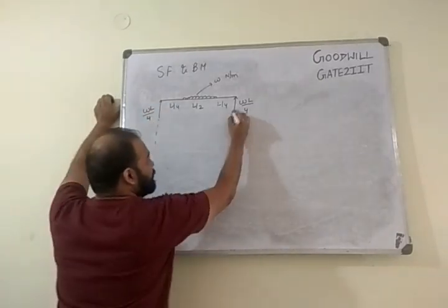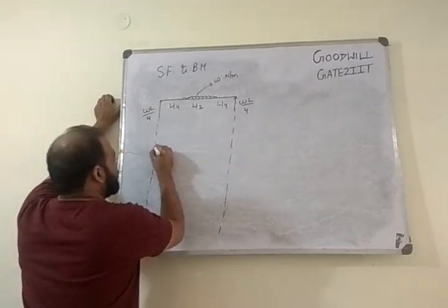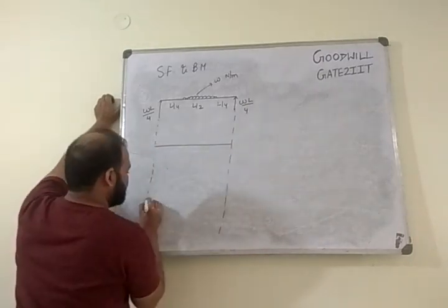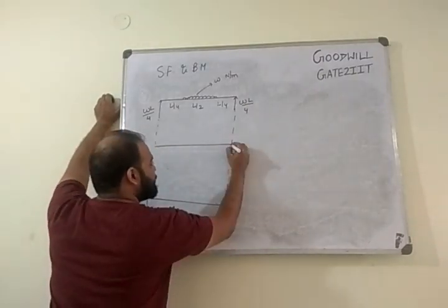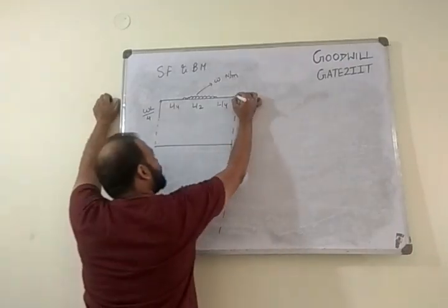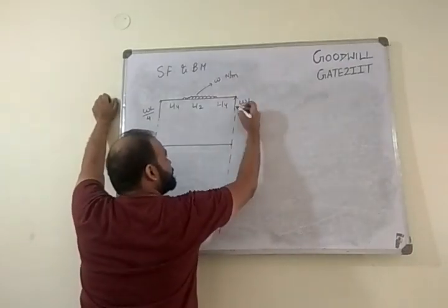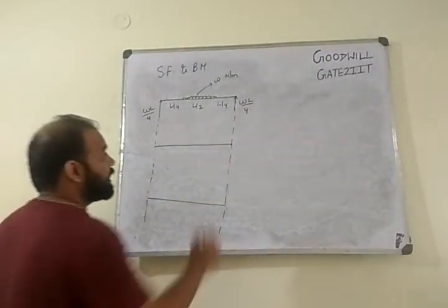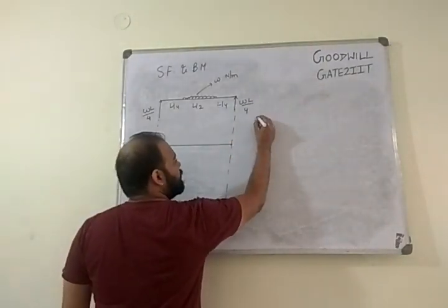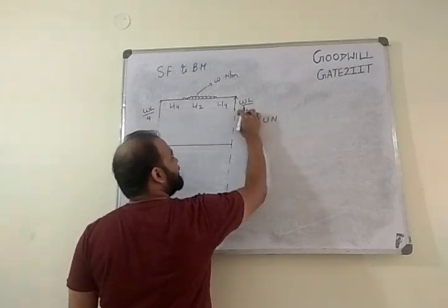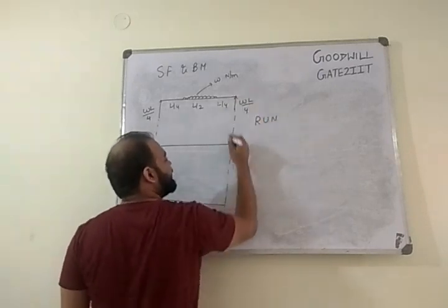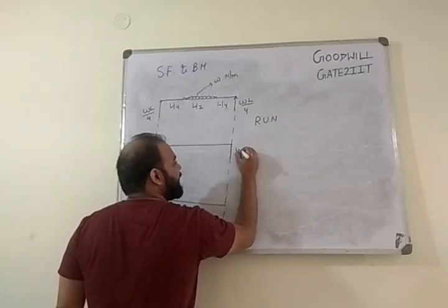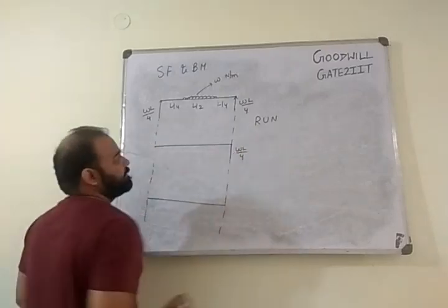Now we'll go for the shortcut and we'll draw the bending moment diagram. Keep properties in mind and then move forward. Tell me what is shear force here. We'll start with 0. There is a point load here, right? So I should have a jump with my sign convention. Right upward is negative. This is on the right hand side, going up negative. So I should come down with a magnitude of WL by 4.